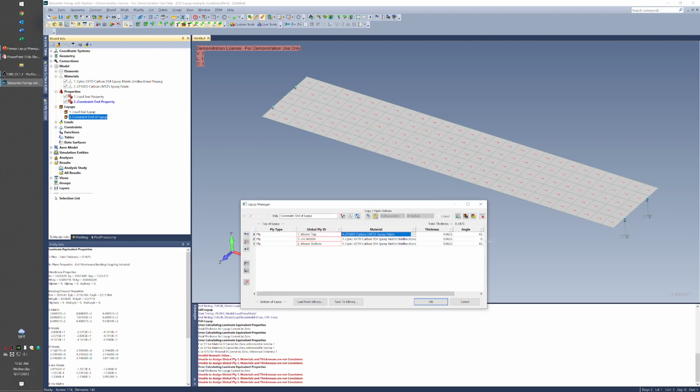It hasn't populated in the model info tree, but you can see by the IDs 4, 3, we don't actually have an ID of 4 or 3. And that's why it's giving us an error message too. It's because the IDs are wrong. Even though the material is technically the same, the thickness is the same, the material IDs are incorrect. So let's do some fixing right here.